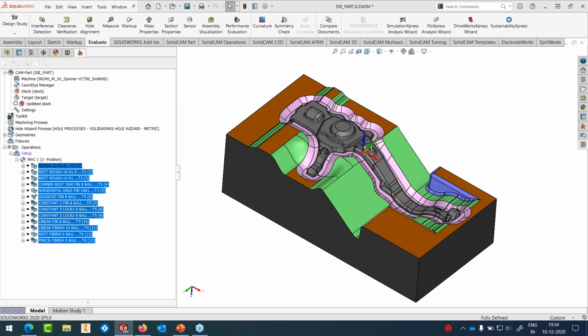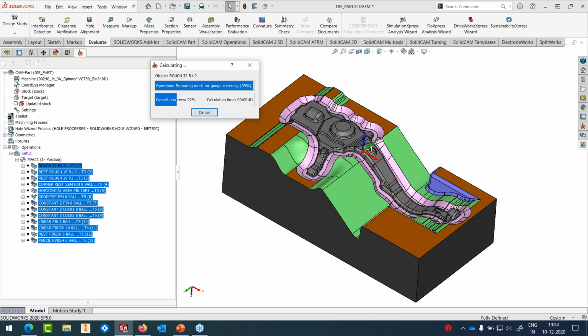As the calculation starts, let's go and look at our slide, because all these two parts that we have seen, majority of them have been finished using constant Z and linear machining. There's nothing more than that, and the rest machining. And in some areas we did constant step over, but there are several other finishing techniques available inside SolidCAM. We also have to look a bit at what turbo machining has to offer. So let's look at the slide.